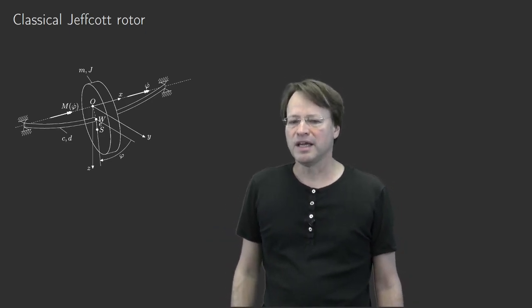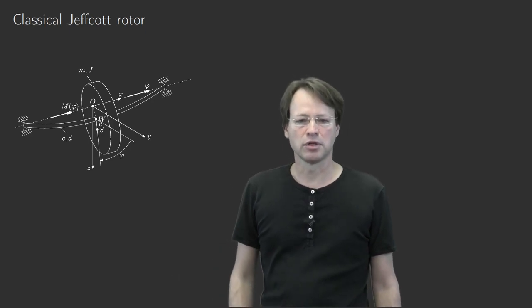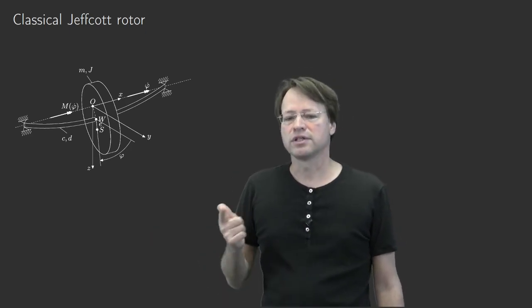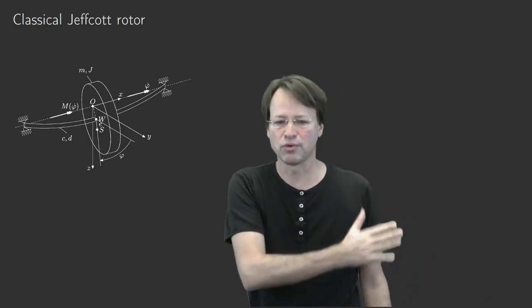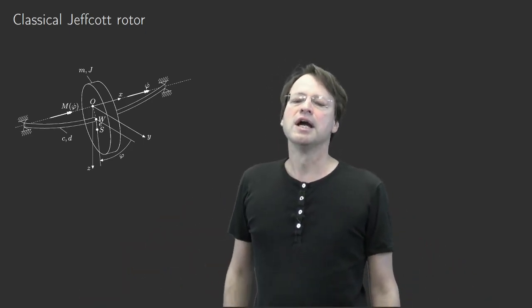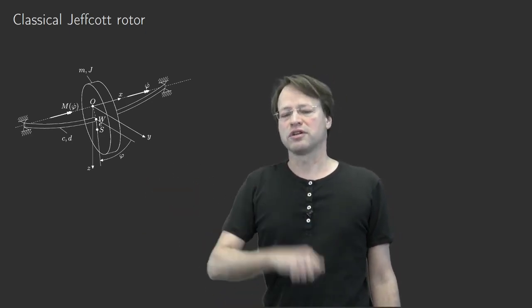Namely, we will somehow separate the mechanical properties that we need in order to describe a vibrating system. What are these properties? Well, we have the mass properties or inertia properties, we have the stiffness and the damping properties. So stiffness and the damping properties, I would say, on one hand, as they provide the restoring forces, and on the other hand, we have the inertia effects.